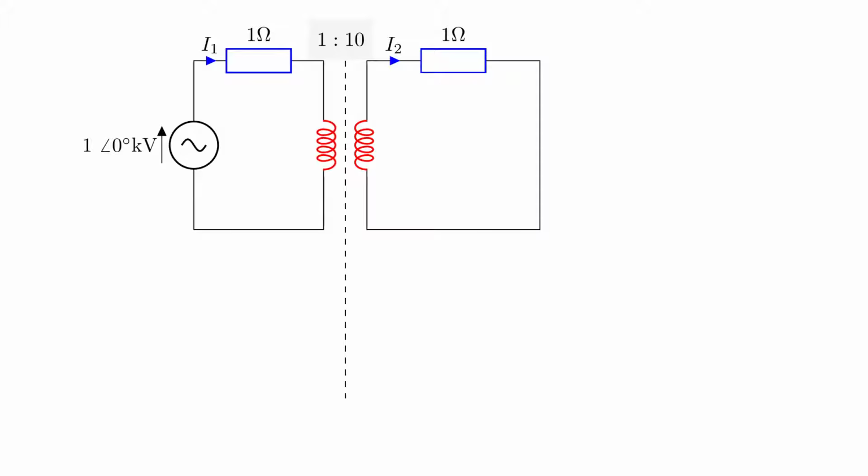Step one of per unit analysis is to split the system into zones. You do this by drawing an imaginary line right through the center of each transformer. You can see here that since we only have one transformer, we have two zones. A power system might have hundreds or thousands of these zones.